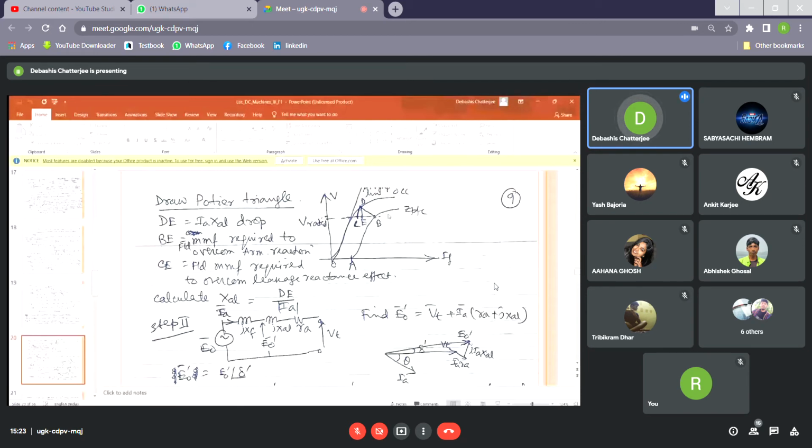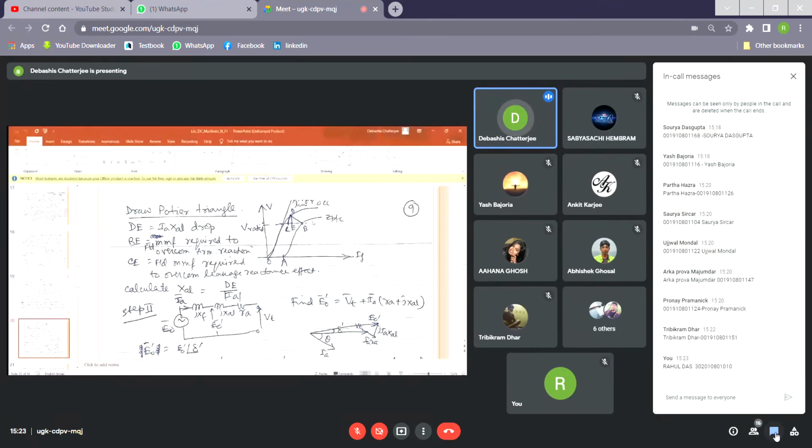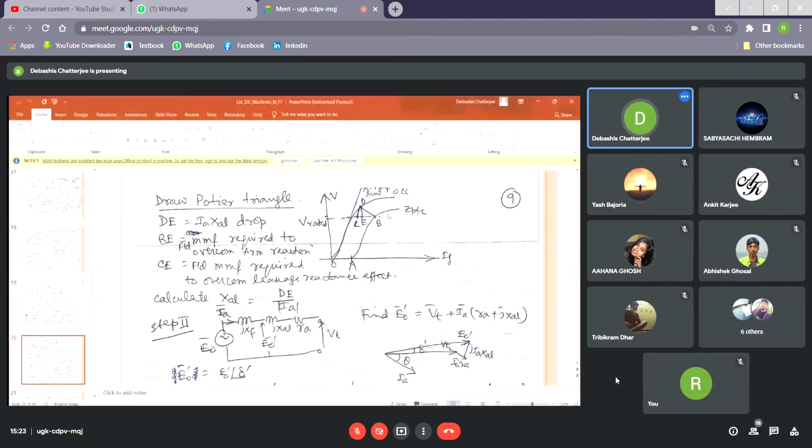When we explained the term ZPF characteristics, zero power factor characteristics, we saw the plot shown in this figure, starting from A, and it has a shape which is almost nearly similar to the OCC. It is like a shifted OCC.